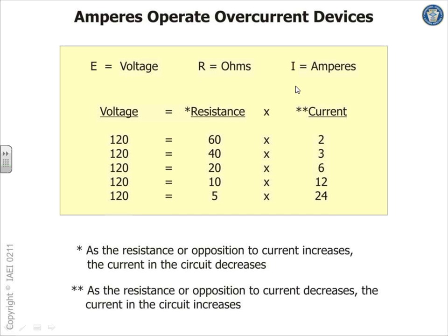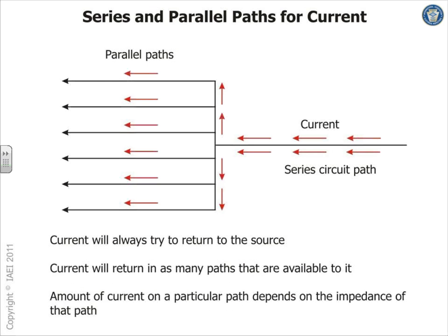So the job of a grounding system, with all these conductors that I bombard you guys with, is to give you a very low impedance path back to the source. The source is the transformer or the generator that generated that voltage. Back to the source fast enough before you create a fire or kill somebody. Is that a novel idea? Otherwise, you could use barbed wire to carry current and it would not be a big deal.